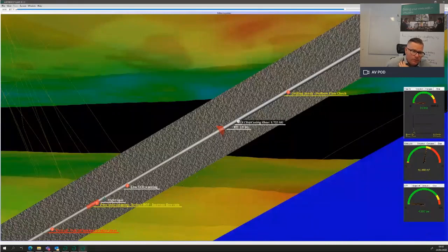We have also some other information here that appeared while drilling. We had a low ECD warning, which is a pretty generic warning, but it tells that the ECD is lower than expected. We also have information about the tight spot. This is a message that is added in by the mud logger in this case, so it's easy to track where it is and to see it afterwards.